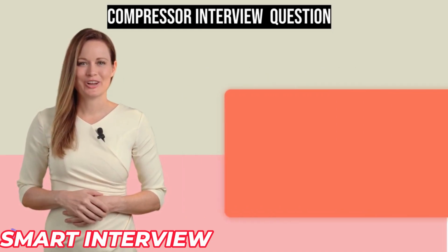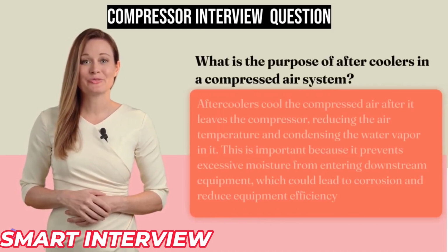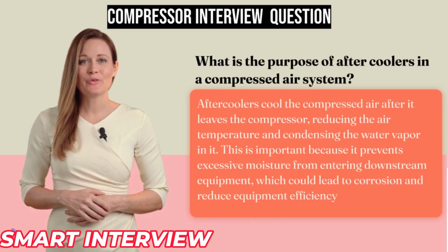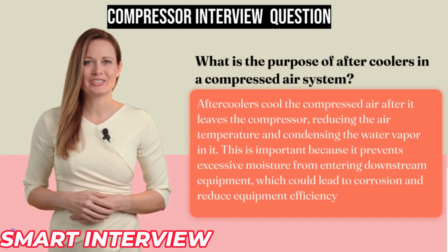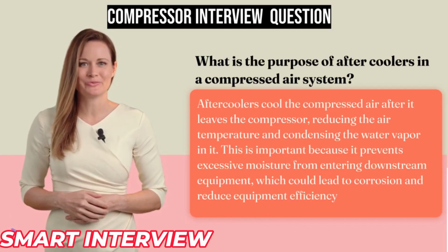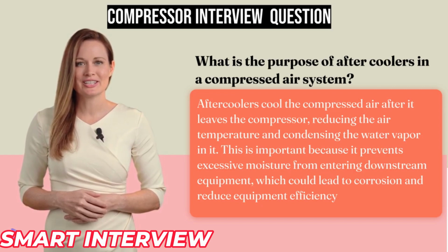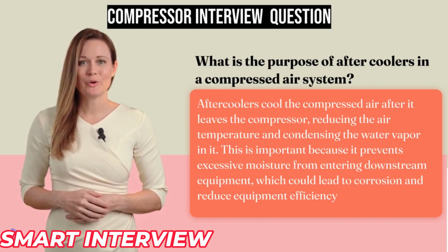What is the purpose of aftercoolers in a compressed air system? Aftercoolers cool the compressed air after it leaves the compressor, reducing the air temperature and condensing the water vapor in it. This is important because it prevents excessive moisture from entering downstream equipment.